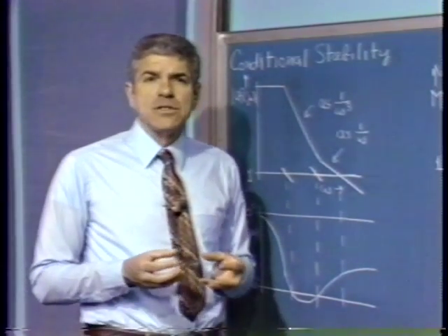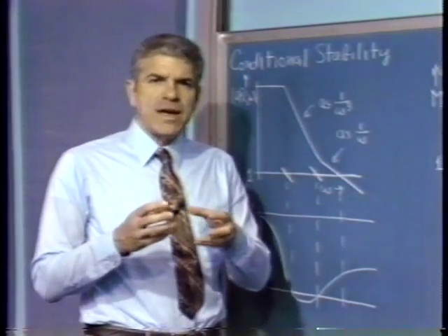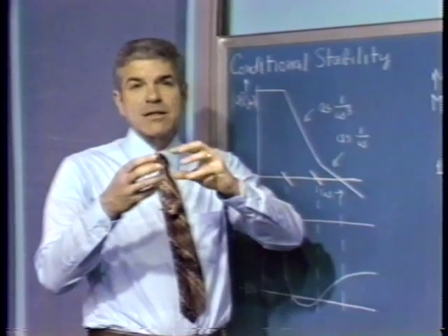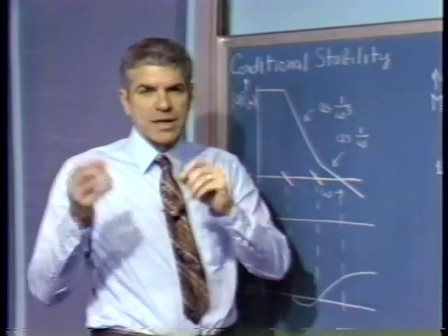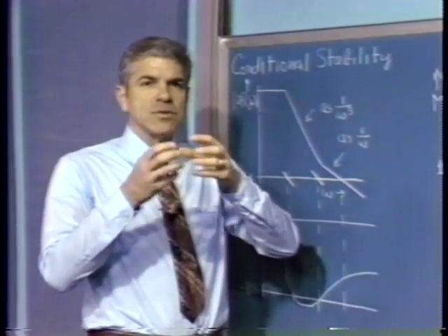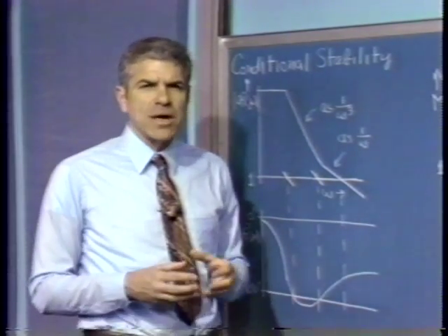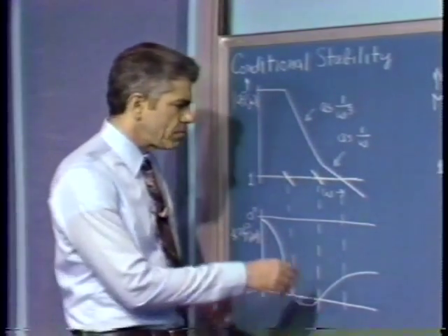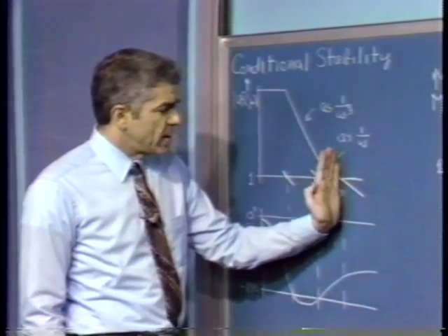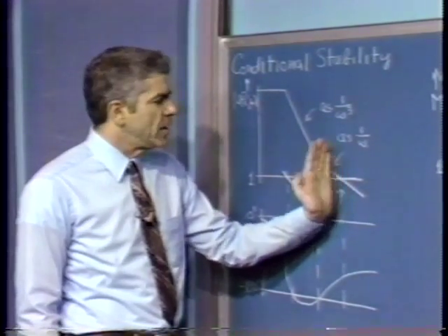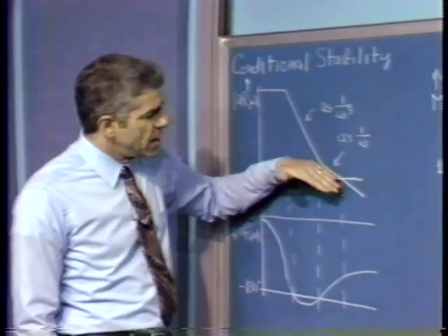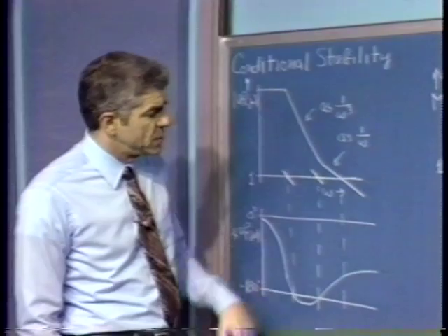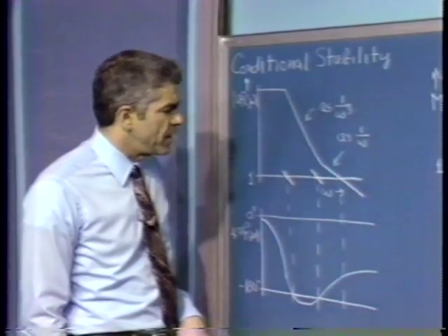If you consider a mechanical system, a servo mechanism, there are effects like resonances in various members in the system that connect the output with the input, or a motor with an output member at sufficiently high frequencies. There are mechanical resonances. Again, it becomes very, very difficult to force the system crossover above those critical frequencies. So in the usually encountered feedback system, there's really some maximum value for the crossover frequency. And if we design a well-behaved system, we'll try to have a slope of something like 1 over s in the vicinity of crossover so that we can achieve adequate phase margin.